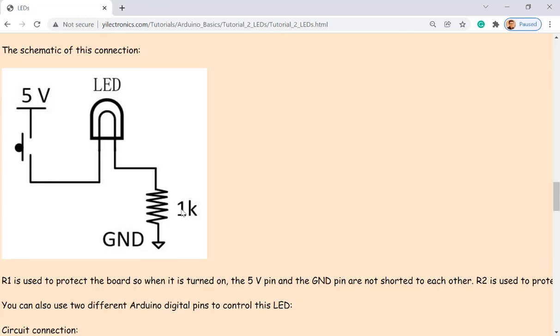So what's the voltage here? Always 0, right? And there's no current, so no voltage drop. That's why it's 0 volts. And here's nothing. Definitely, there's no power. It won't turn it on. So what's the name of this resistor here in this case? It's called a pull-down resistor. It's pulling this pin down to the ground.